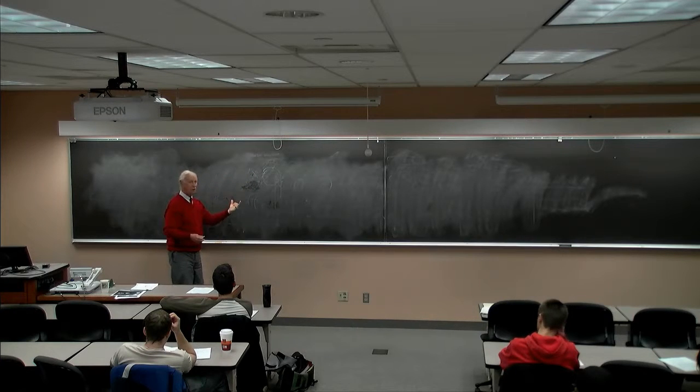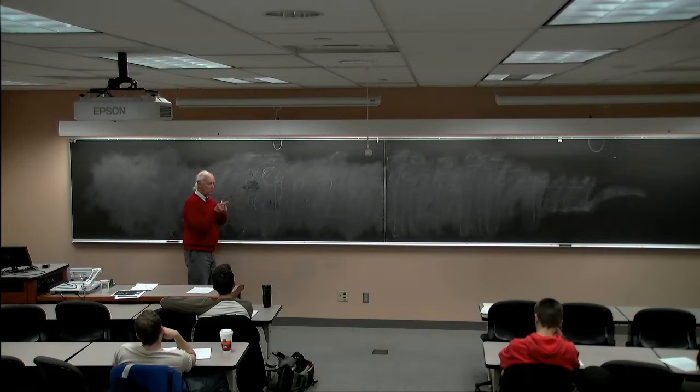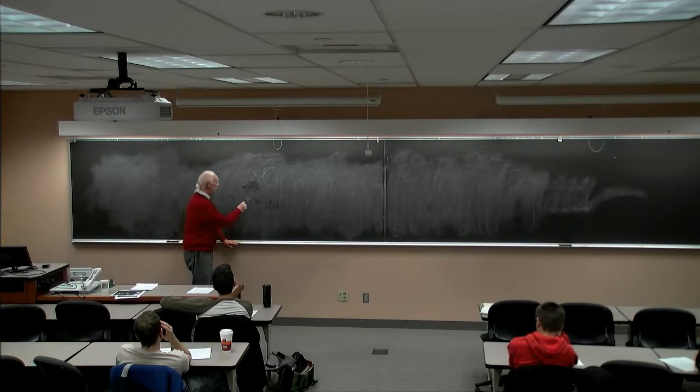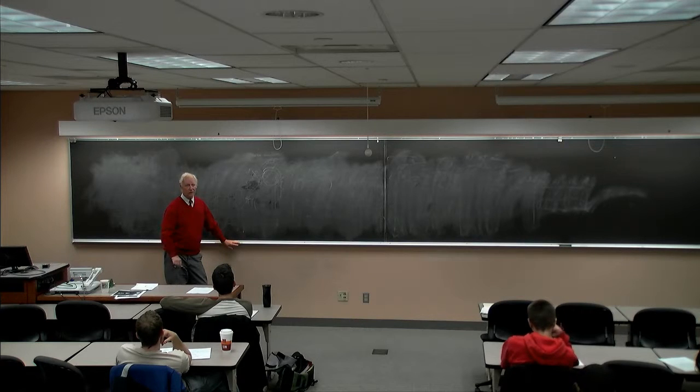Then the other one was what I alluded to. Hey, make that area really small. I mean, make it a skinny, skinny loop so that it's like this, and then you don't get much B field, not much flux fluxing through there, so dΦ/dt is small, and yeah, that's another solution. But I told you, that makes the characteristic impedance of that line perhaps impractical, okay? So then it's a solution, but an impractical solution. So then what I ask you to do is a third solution. And that's the one I want you to work on.